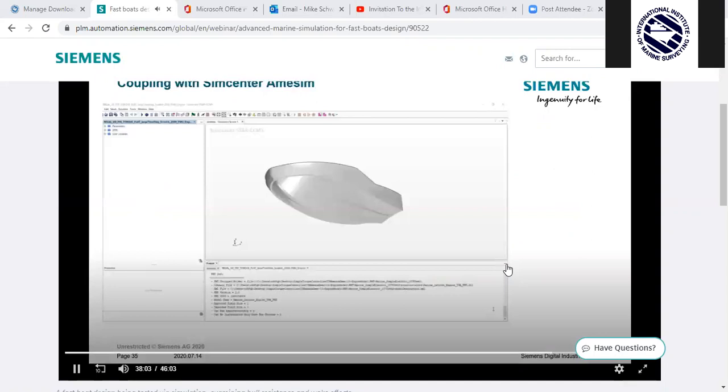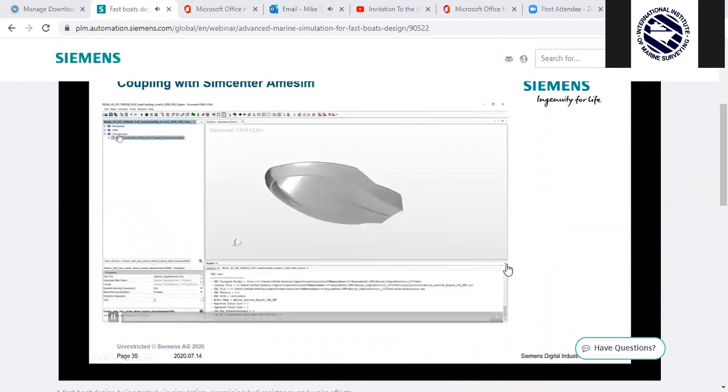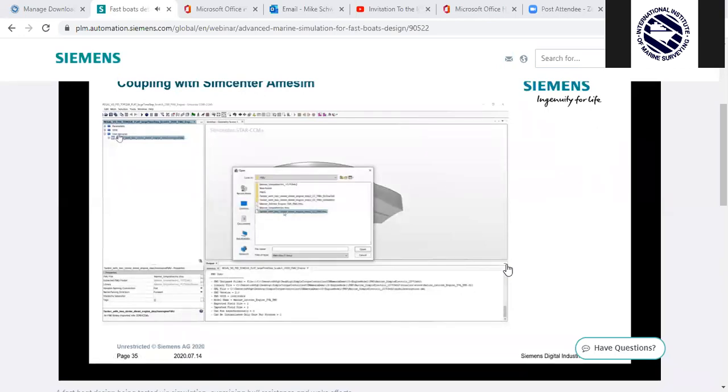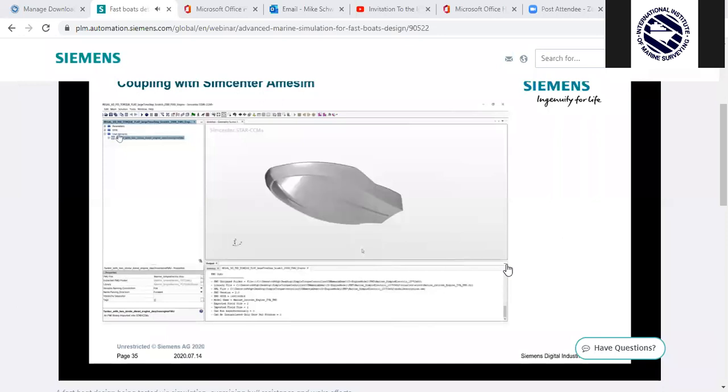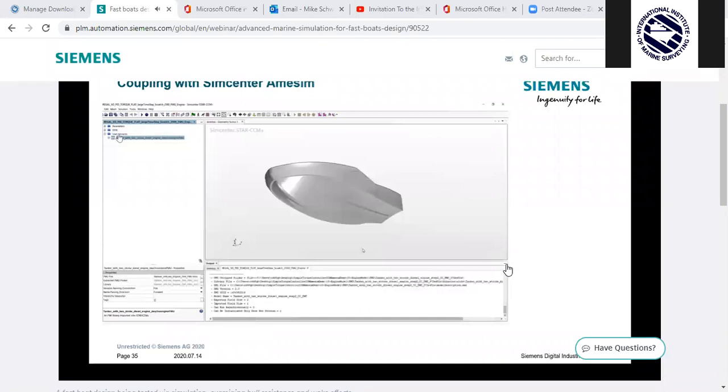Similarly, swapping out an engine model is also pretty easy. So again, we have just our library file. Here we have an electric file incorporated into an FMU file. FMU stands for Functional Mock-up Unit, which is an industry-wide accepted standard for storing the 1D data from Amesim. So if everything in Amesim is labeled the same throughout the models, then we can simply swap out these FMU files. So here we swap from an electric motor to an outboard, to a two-stroke motor, to a diesel motor, all by simply changing your FMU library file.